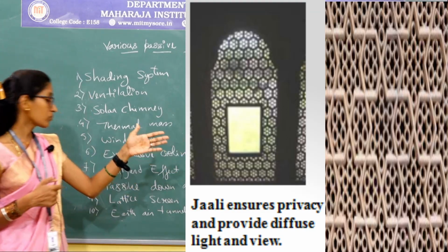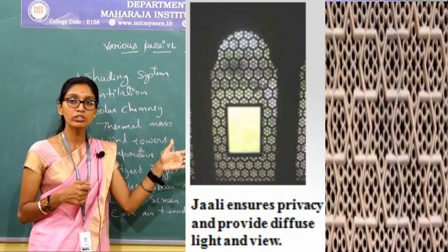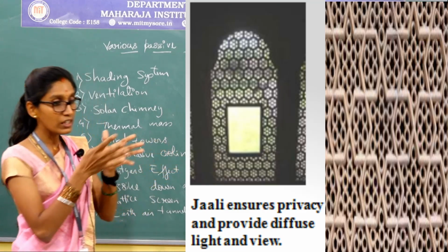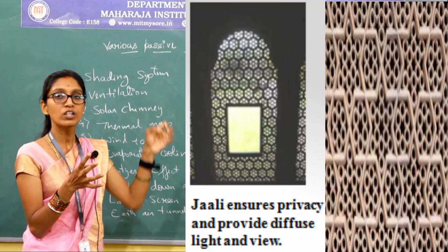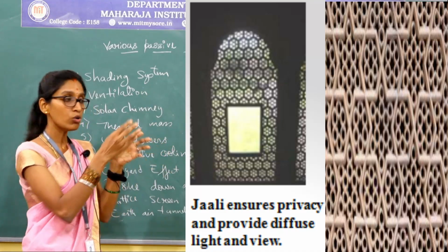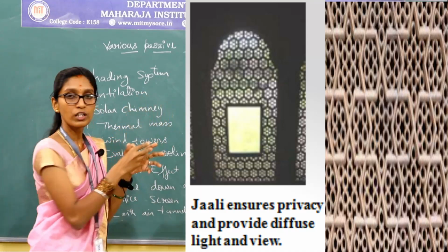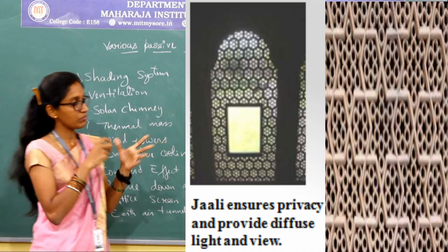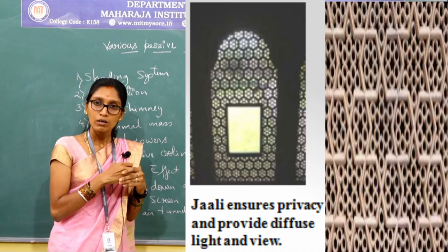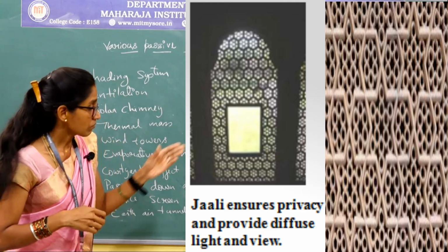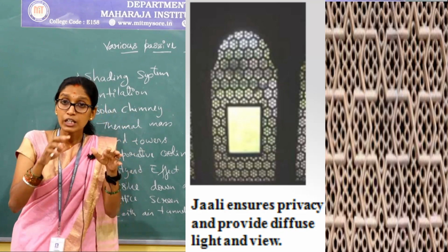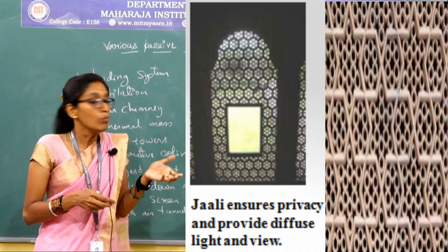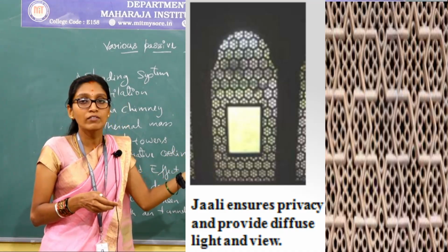can see how the jali or the lattice screen looks like, and how the diffusion of the light is taking place, and how the interior cannot be seen from the exterior when it is too sunny, and how a good visualization can be provided from the interior to the exterior environment. At the same time, it is providing privacy.